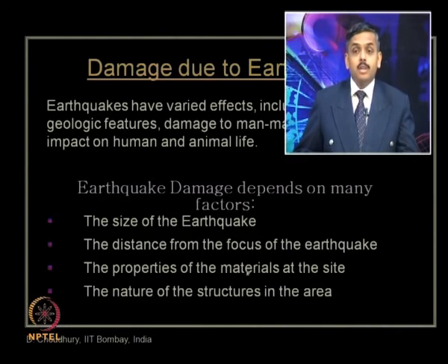Suppose, as I have already given the example of Mexico City, it was located on soft soil deposits. In Mexico City, all the ground structures are located mostly on the soft soil deposit, and the bedrock acceleration at large depth from the ground surface was pretty low in magnitude, which was not supposed to cause major earthquake damage, because the size of the earthquake was pretty small. And also the distance from the epicenter of that earthquake during that Mexico City earthquake was far away from the site of concern of Mexico City.